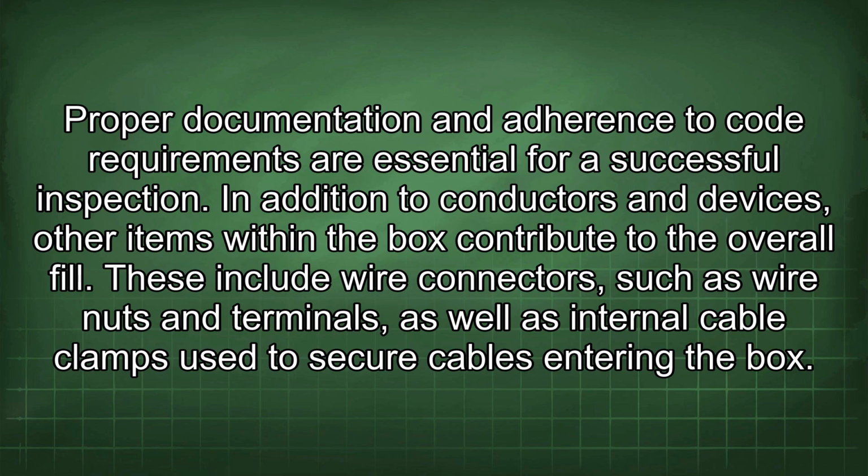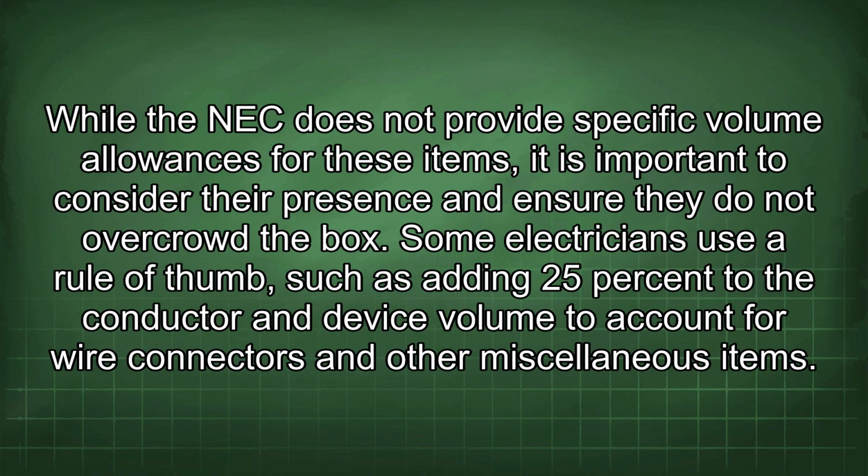In addition to conductors and devices, other items within the box contribute to the overall fill. These include wire connectors, such as wire nuts and terminals, as well as internal cable clamps used to secure cables entering the box. While the NEC does not provide specific volume allowances for these items, it is important to consider their presence and ensure they do not overcrowd the box.